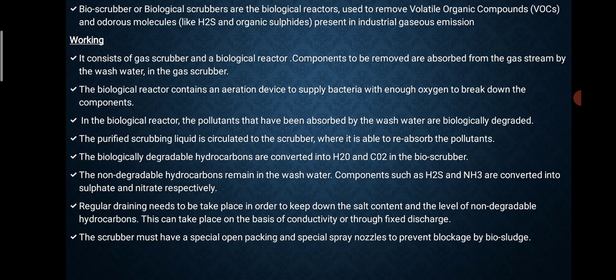Regular draining needs to take place in order to keep down the salt content and the level of non-degradable hydrocarbons. This can take place on the basis of conductivity or through a fixed discharge method. The scrubber must have a special open packing and a spray nozzle to prevent blockage by biosludge.